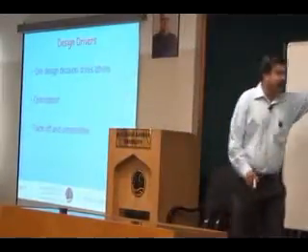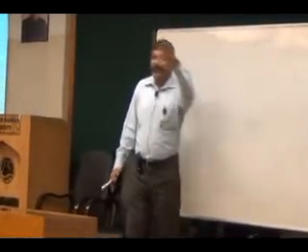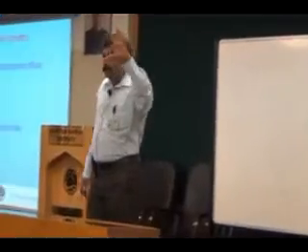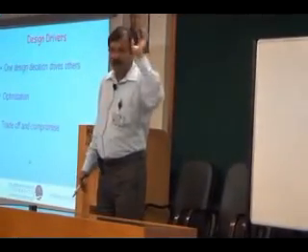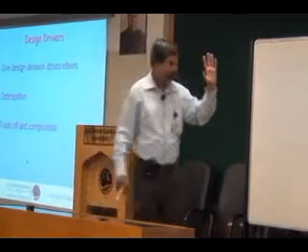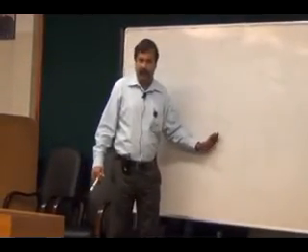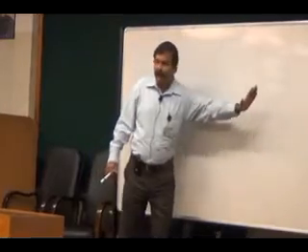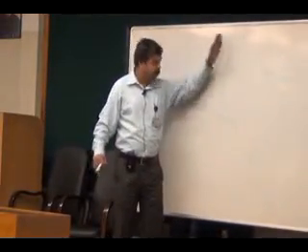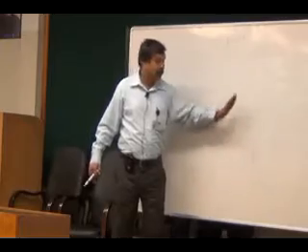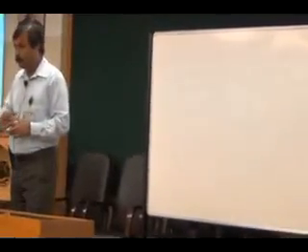So there is something called a lift, there is something called a weight. When an aircraft is cruising at a constant velocity, the lift will be equal to the weight, thank you for correcting me. The lift will be equal to the weight and the thrust will be equal to the drag.